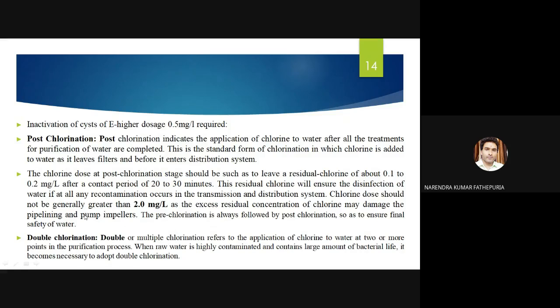Chlorine doses should not generally be greater than 2 mg per liter, as excess residual concentration of chlorine may damage the pipelines and pump impellers. Pre-chlorination is always followed by post-chlorination.